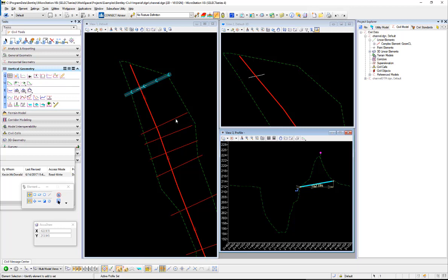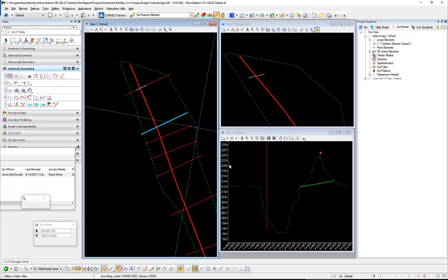We're going to generate these 3D lines along all these sections, and then we're going to import those into a new terrain model. And right now we have manipulators on that profile that we drew, so it allows us to make changes and to preserve our design intent there. So I want to show you how that works some more.